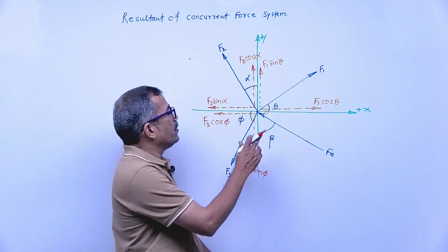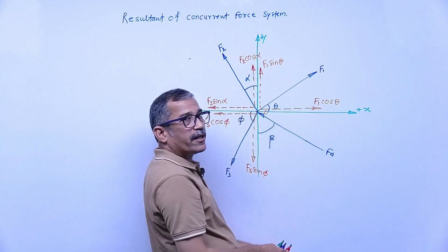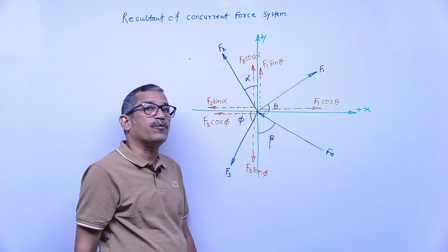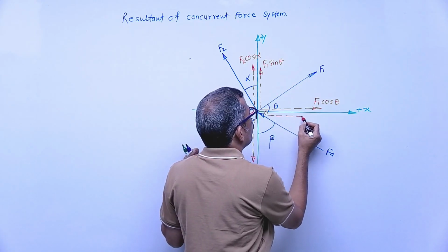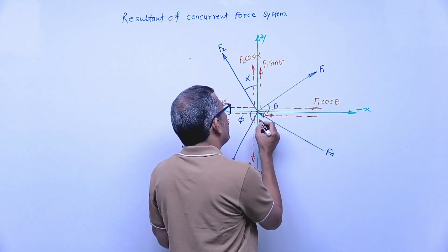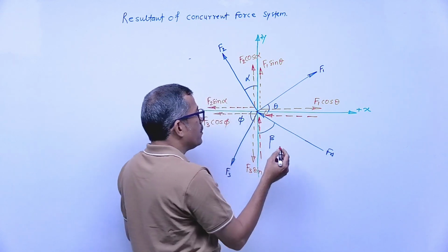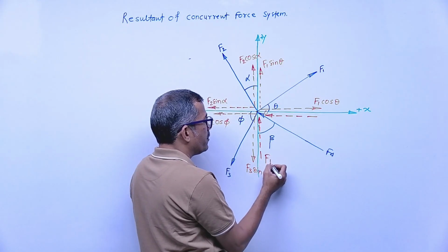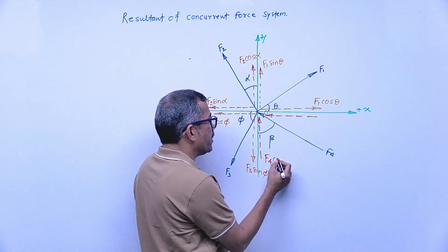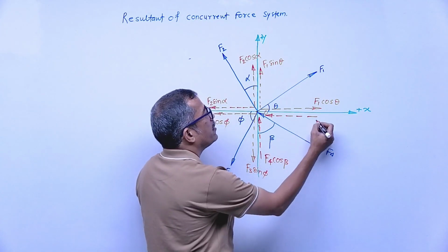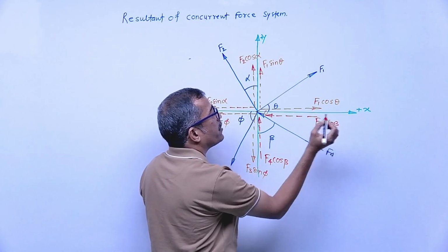Okay. F4 force is acting at this point, towards the point, right? It is towards the point, meaning push in nature. Components must be push, meaning towards this point. The vertical component is also towards this point. The angle is with vertical. The vertical component we get is F4 cos of this angle. The horizontal component is F4 sine of beta.